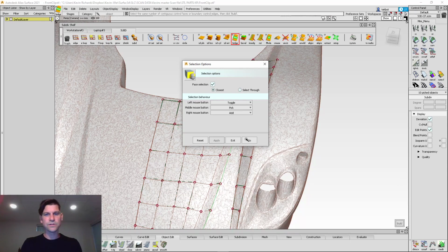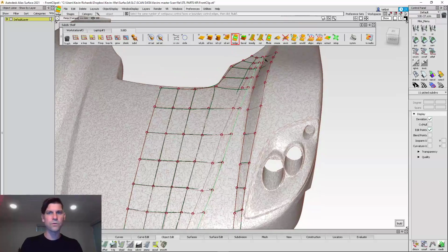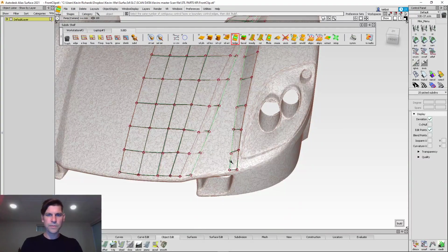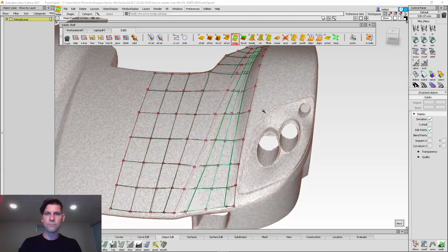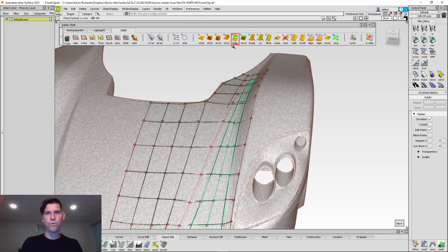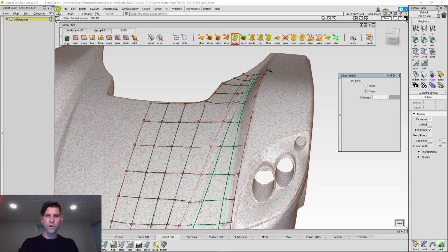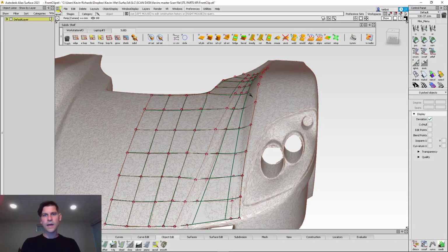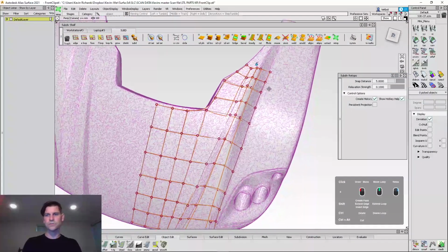But you want to set this to your add. Great. And then what that allows you to do is select one point or edge, hold Shift, and add the entire loop of selections between those. And we'll bridge. And we could go with two divisions here. Where's my interface? It's stuck on the other screen. There we go. And we'll just change the divisions down to 1, right? And then I'll query edit, and I'll go back into the tool. And now we're right back into the topology tool.